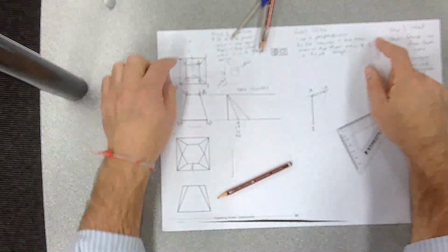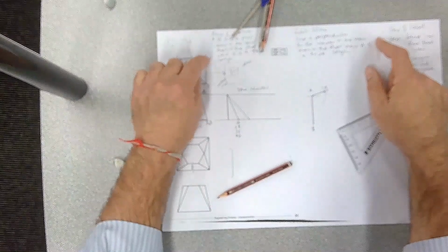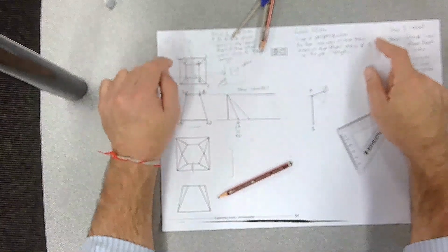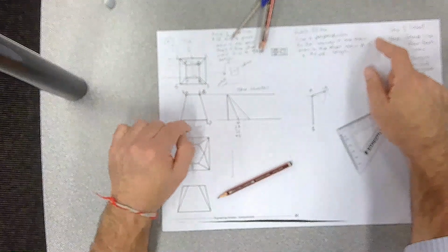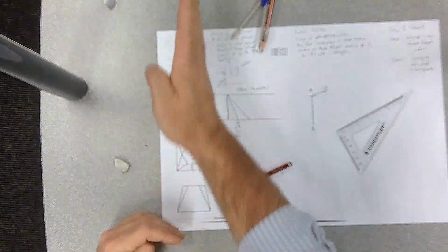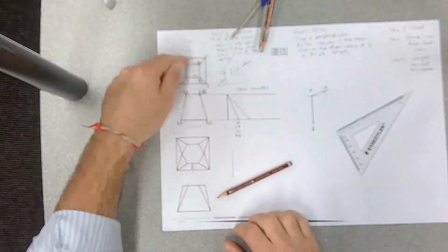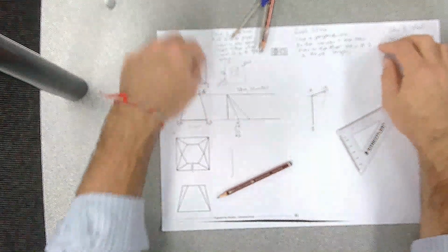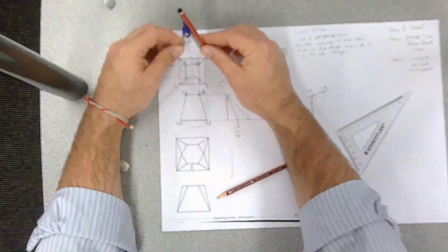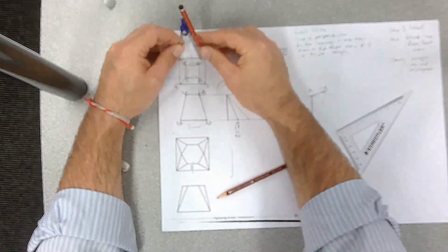Okay, on here, because we're working on this side. So we're going 1 to 2. You can see that this is perpendicular to me, so 1, 2 is a true length. Same deal here. If I look at this view, 1 to 2 is, my axis of symmetry this way, a horizontal line. In the other view, I can measure off this one or this one. It won't make any difference. We're going to use the top view, be consistent. 1, 2, we know it's a true length.